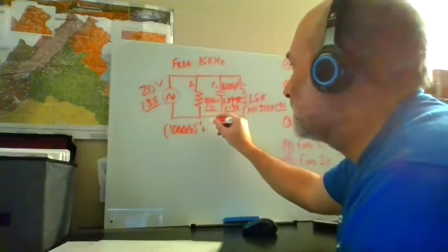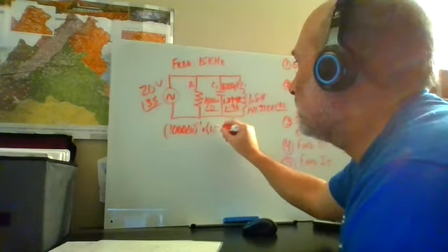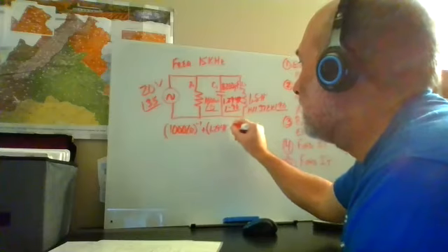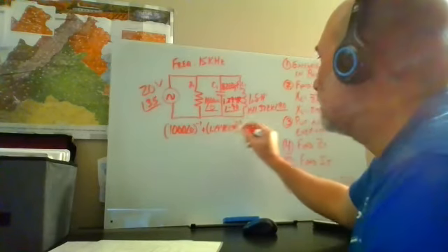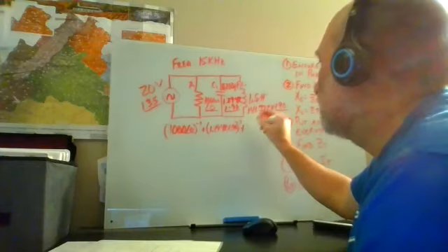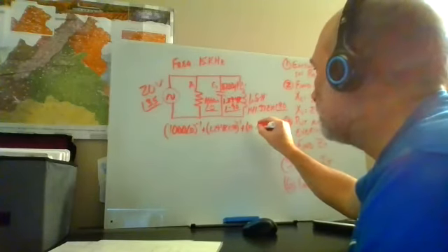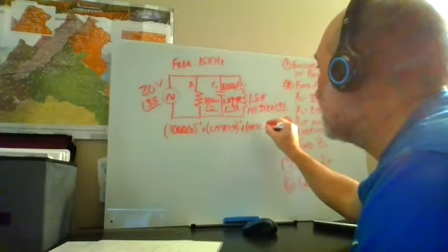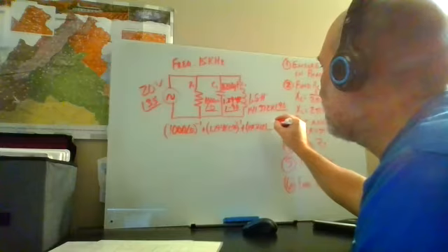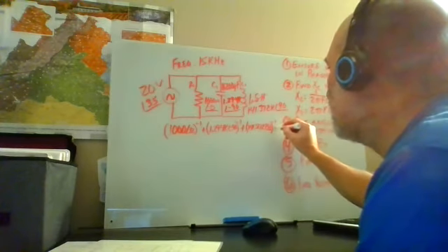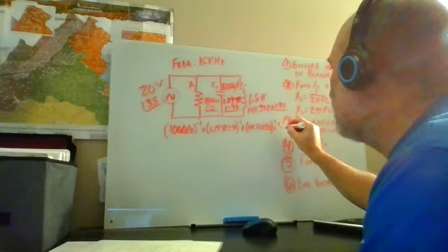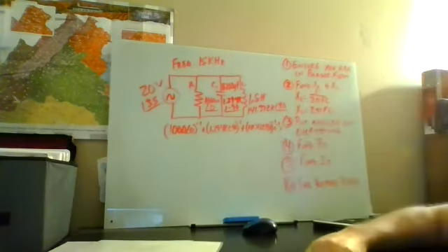Then I hit plus, open my parentheses again, put 1.924K at an angle of negative 90, close my parentheses, shift reciprocal, plus, open my parentheses again, 141.372K at an angle of 90, close my parentheses, shift reciprocal, then I hit equals, I hit shift reciprocal again, and then hit equals, and I get my answer.